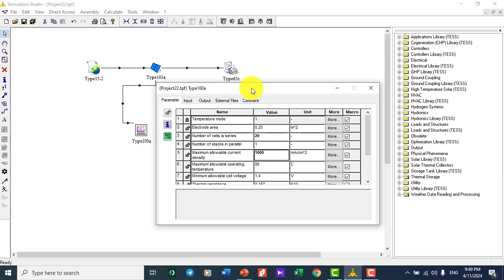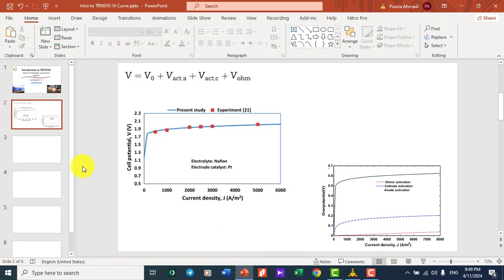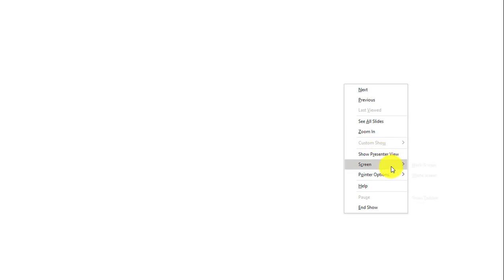Okay. So if I can show you here, this is really interesting. Let me just use the pointer and pen here. Okay, so let's say that, as I told you, in the electrolyzer I have I, which is current density. Then with this I can find V Nernst, V activation, V ohmic, and the overpotential of concentration.